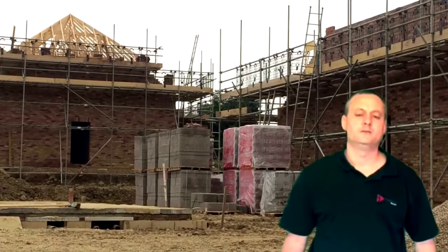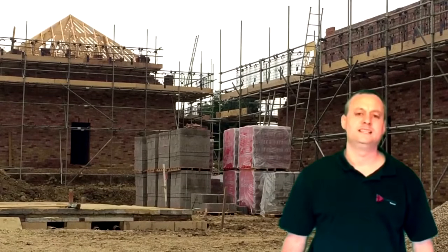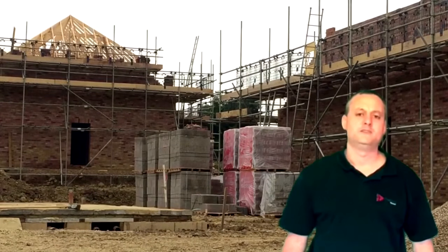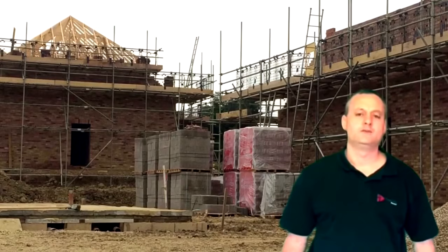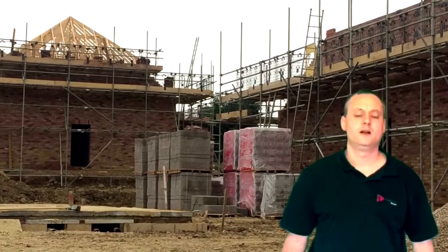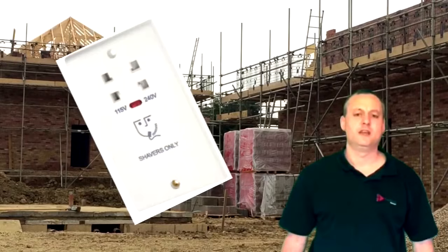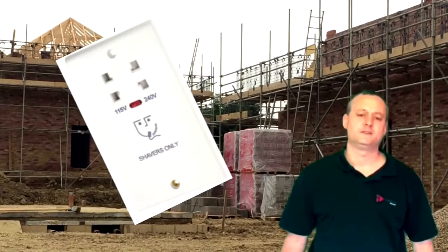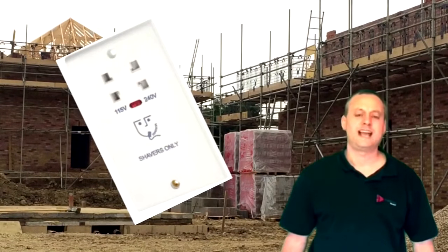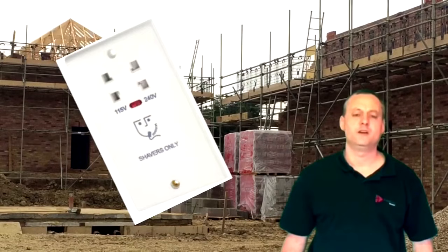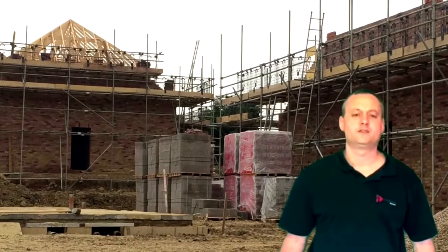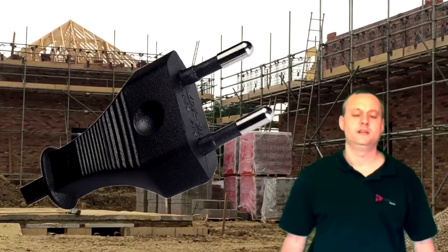We will go on in the classroom to look at SELV transformers in a later set of notes as well, and applications for them. We also looked at isolating transformers in the form of a transformer that supplies a shaver socket in a bathroom. This could still be at 230 volts, but again has no connection to earth on the outgoing side. Therefore, the shaver inserted into the socket only has 2 pins. The earth pin is missing.